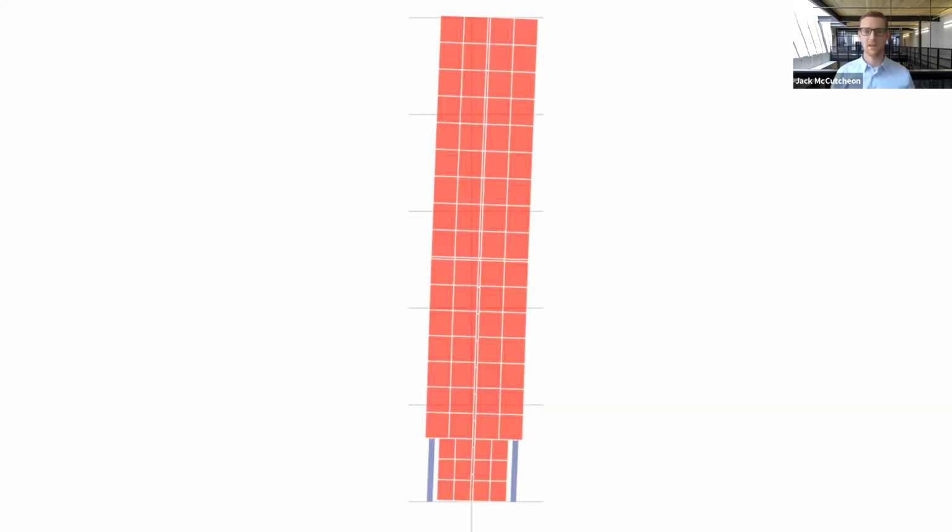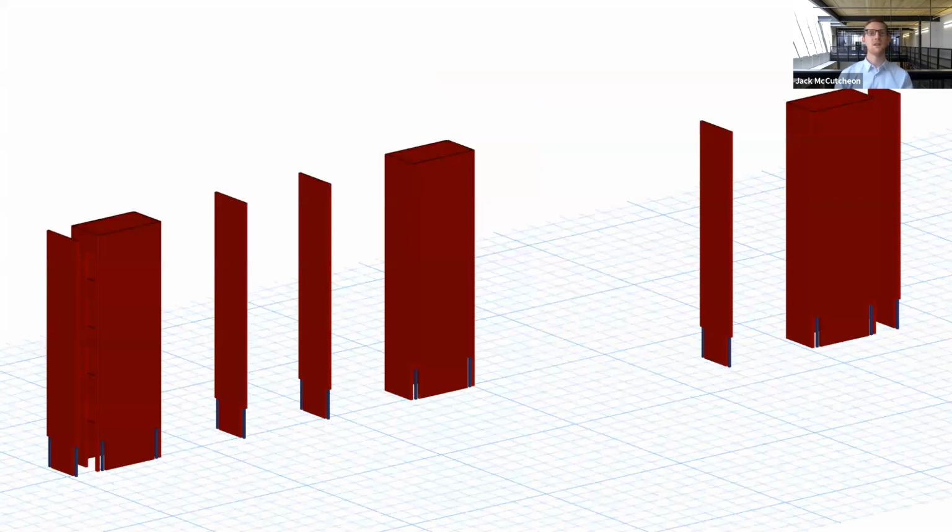So when we go to model and design all these buildings, as Katie mentioned, a lot goes into the modeling. So we need to identify all the panel sizes, the stiffness of each panel, stiffnesses of the spline connections and joints between panels, as well as the stiffness of our BRBs. If we look at an isometric view, I've stripped down everything in the building here except for our shear walls so you can get a feel for the geometry. Each of the walls has a BRB down at the corner, the bottom level. And in addition to that, we have 3 cores.